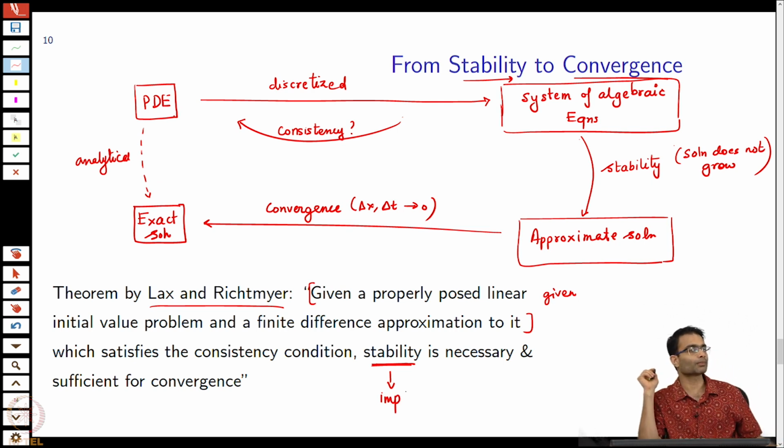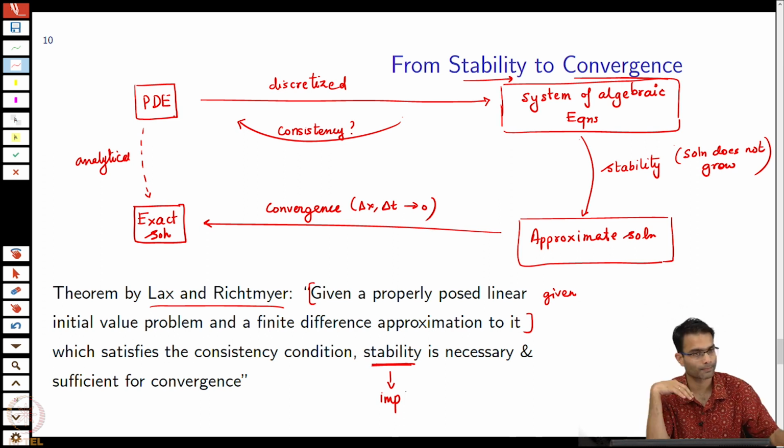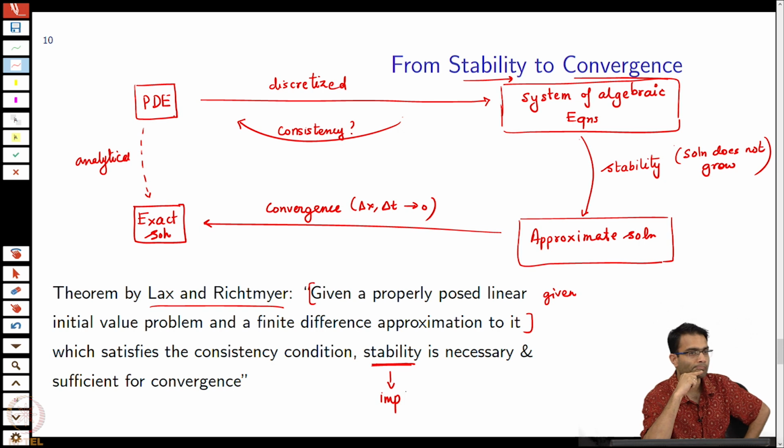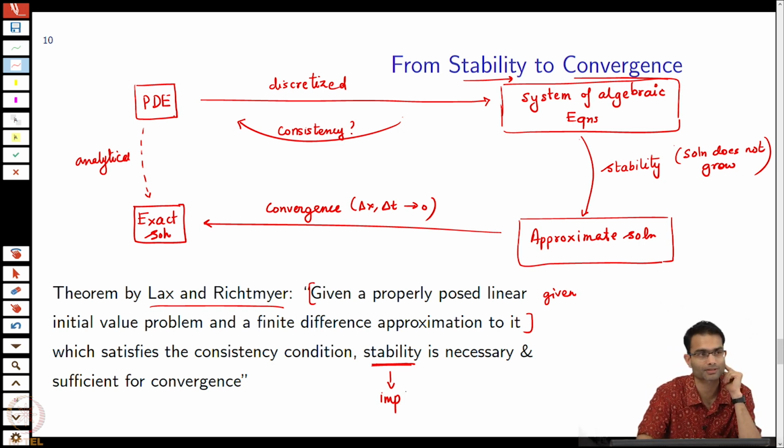Okay. So, when you look at commercial FDTD software, one of the most important knobs is this Courant stability factor. You have to make sure that you are obeying it such that your stability is satisfied, and therefore convergence is also satisfied. Okay. Any further questions on this? As I mentioned, in practice, apart from just making sure that the Courant factor is satisfied, there is not much practical use as an engineer that we will have for this.